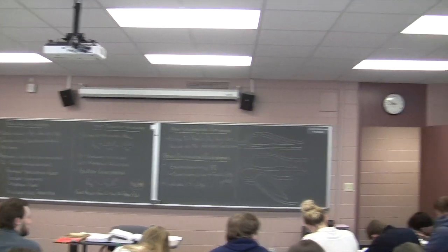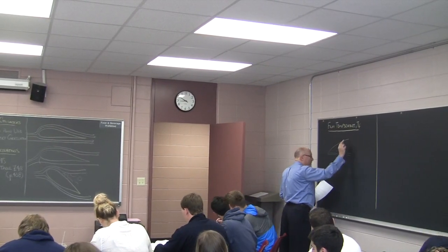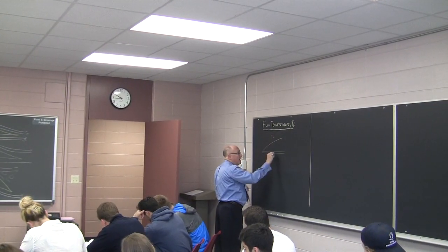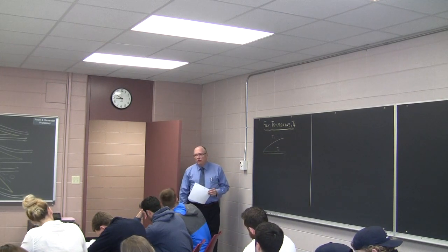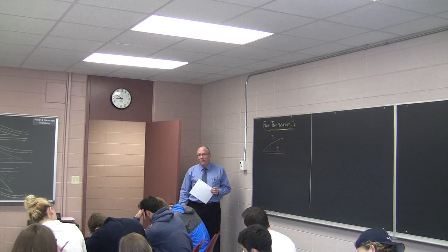Film temperature. We have flow over a surface. Let's draw for a moment a flat plate. We have the formation of the boundary layer, and we'll have two temperatures here. We'll have T infinity out here, and we'll have some T surface. That's typically the case. You notice that we've been assuming all along that these are isothermal surfaces. Okay?